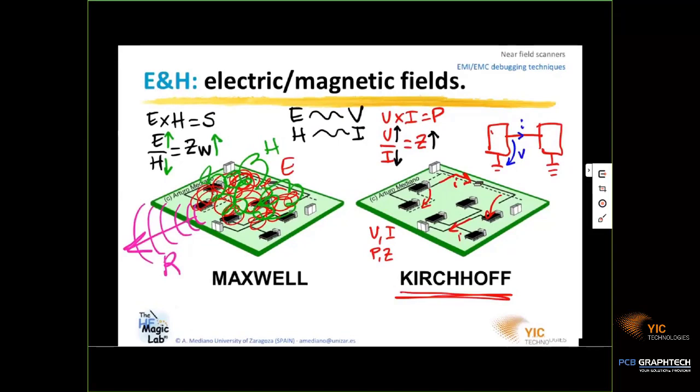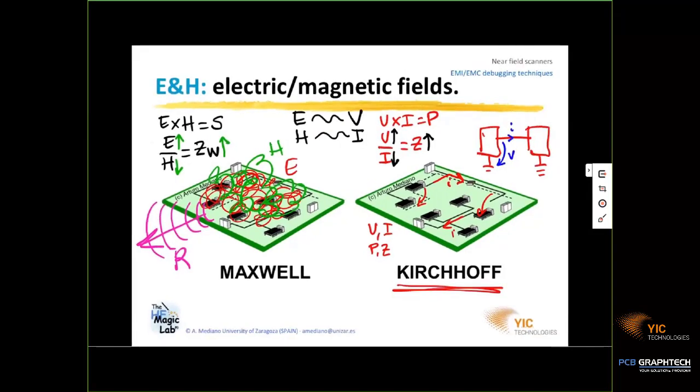This radiated energy needs some specific element in your system. You need to have in your system some kind of antenna. So for example, if you are designing a wireless system, you will prepare some small PCB trace or some small wire to be able to radiate 2.4 gigahertz, because this is the signal that you want to radiate or to pick up from the environment.